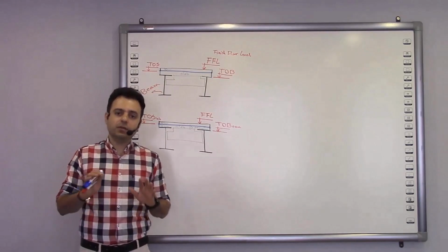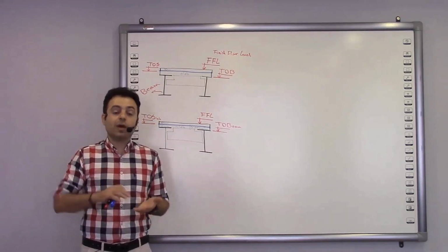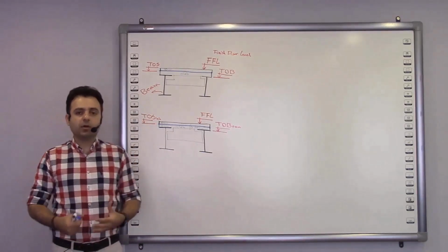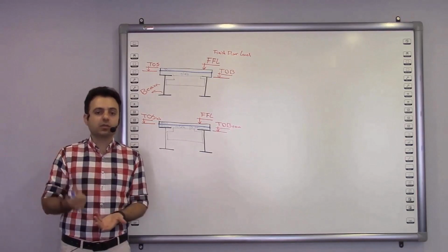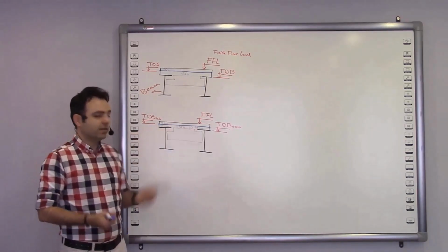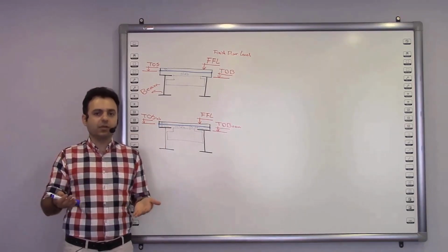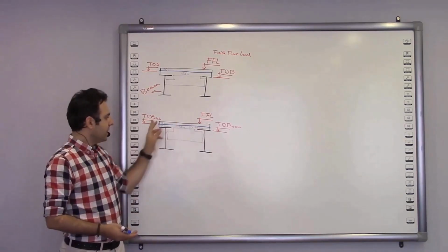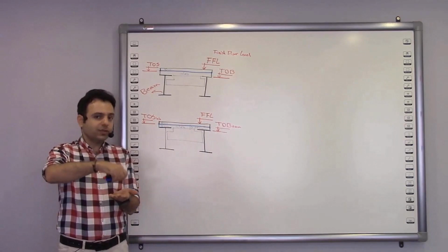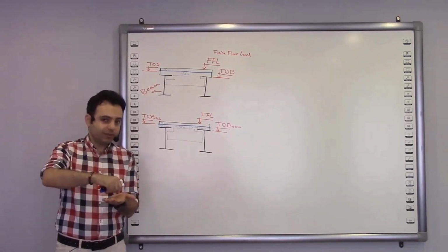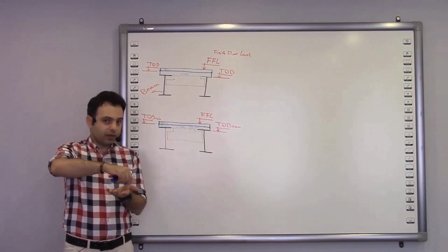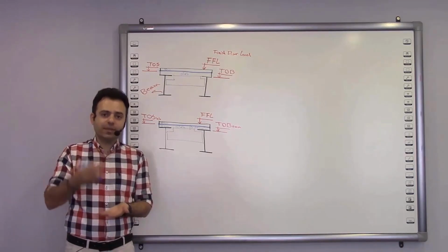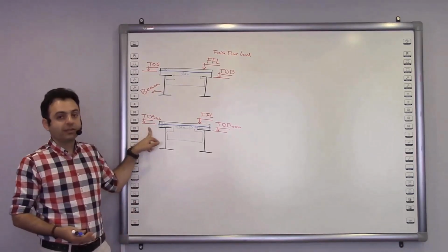Now let's go for the walls. I explained the levels, you know what happens on each one. Now we want to go for drawing the walls. But one question, for example, I want to draw a wall in Revit. Which of these levels does the wall start from? Imagine while building, for example, you have a wall and now you want to really build it. On which of these should we place the first brick? Let's imagine it this way. Should it be on the beam or the concrete or even the ceramic? Well, definitely we start the wall from the concrete, or we should say from TOS.